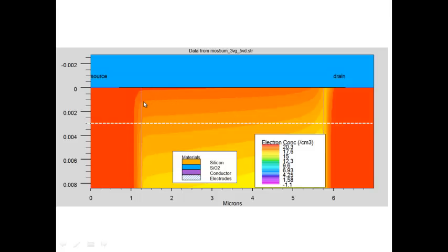If I look at the electron density, you see that it is of course very high here, then it decreases, and eventually becomes negligible. Typical inversion layer thicknesses would be around maybe 30, 40 angstrom. These vary. So a 30, 40 angstrom inversion layer thickness is there, but we are neglecting that. We are saying the entire inversion charge is located right at this particular interface.